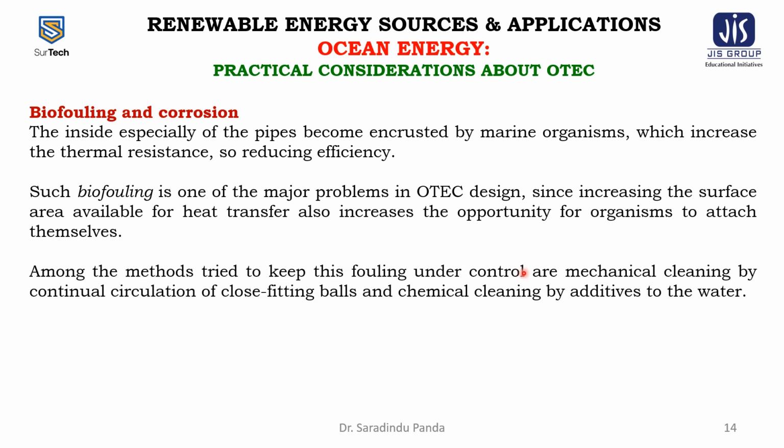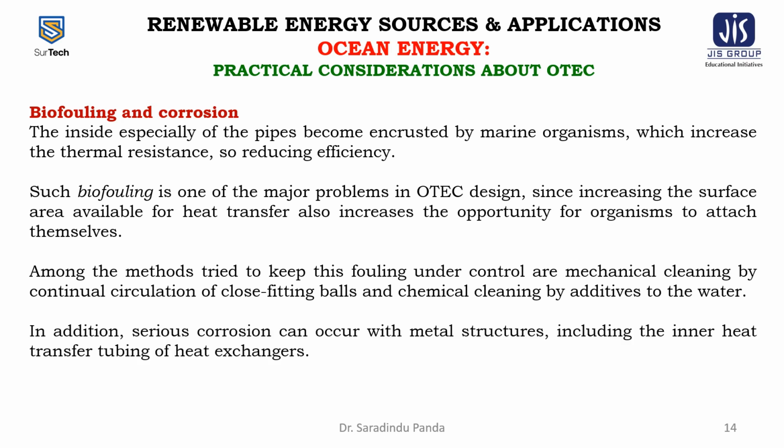Among the methods tried to keep this fouling under control are mechanical cleaning by continual circulation of close-fitting balls and chemical cleaning by additives to the water. In addition, serious corrosion can occur with the metal structures, including the inner heat transfer tubing of the heat exchanger.